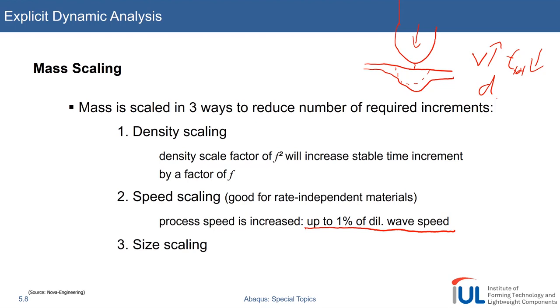But even if the elastic responses are rate independent, and so are the plastic material responses, even then you will see these dynamic structural effects like wobble. So if you see stuff like this happening, you have to reduce the punch speed, because you have increased the speed too far.